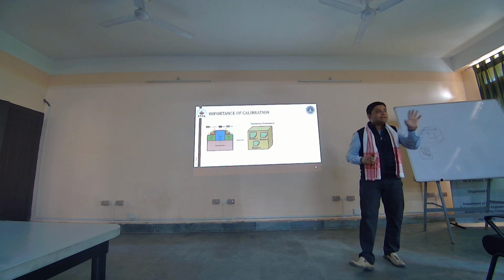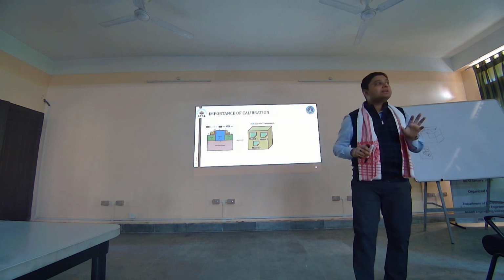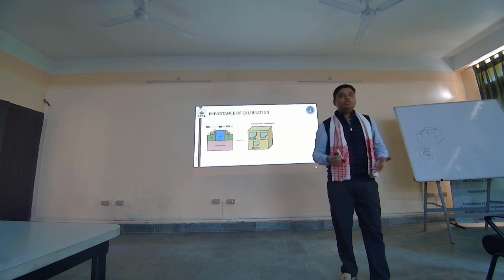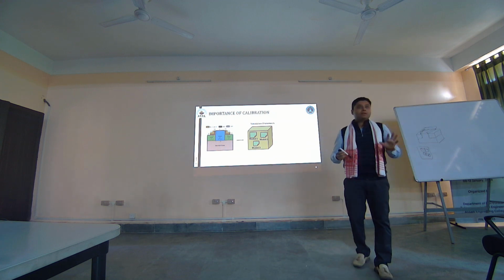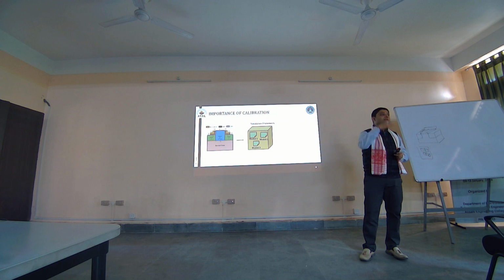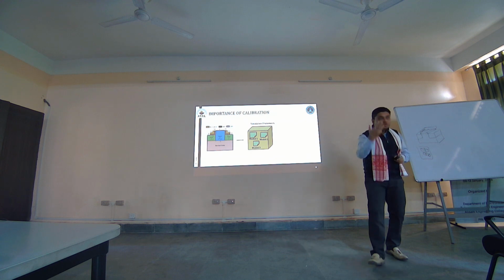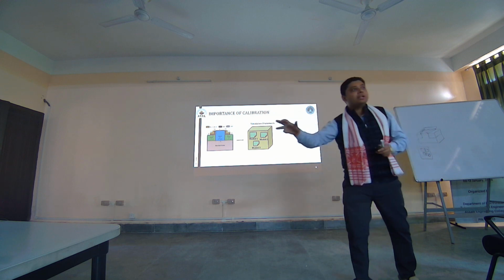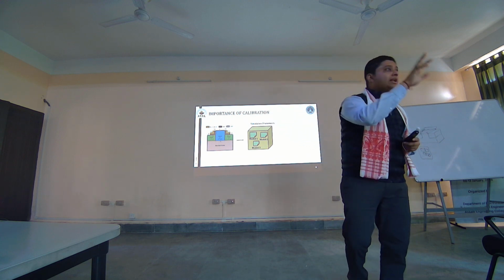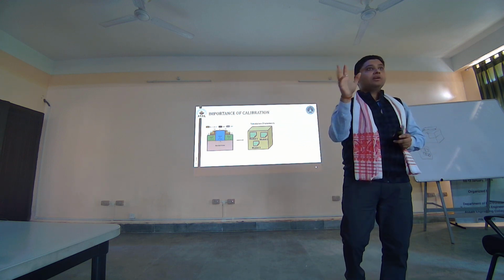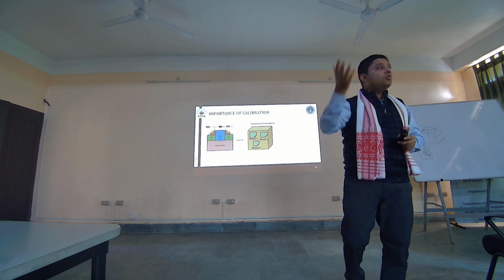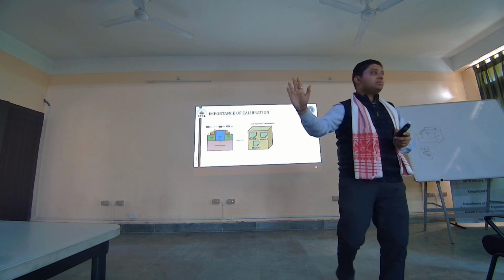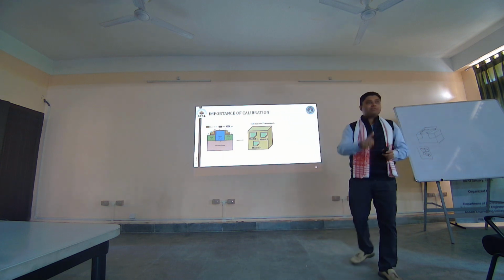So to understand a simulator, first of all, you have to understand what device models it can use. For example, if you have the drift diffusion model, you have to know what the parameters of the drift diffusion model are. If there is a tunneling model, you have to understand whether it is local tunneling or non-local tunneling. So you have to know the simulator first before simply sitting and doing your simulation. That is the first one.